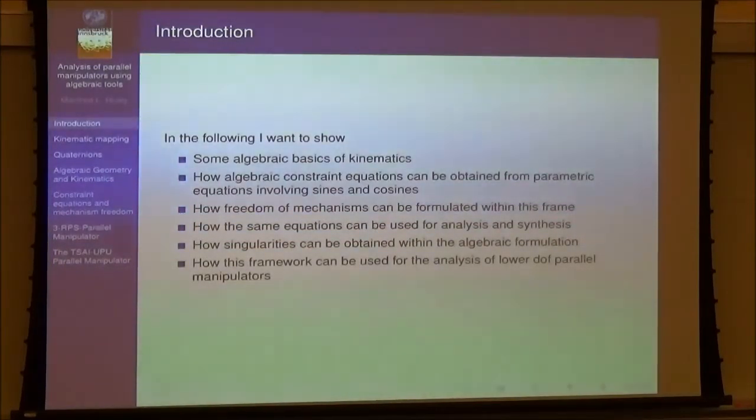And this framework can be used for the analysis of lower degree of freedom parallel manipulators. This type of manipulator has become of major interest in the field, maybe because when you have a specific task where you don't need all degrees of freedom, you want to design a manipulator, synthesize a manipulator, which will do this task with less actuation.